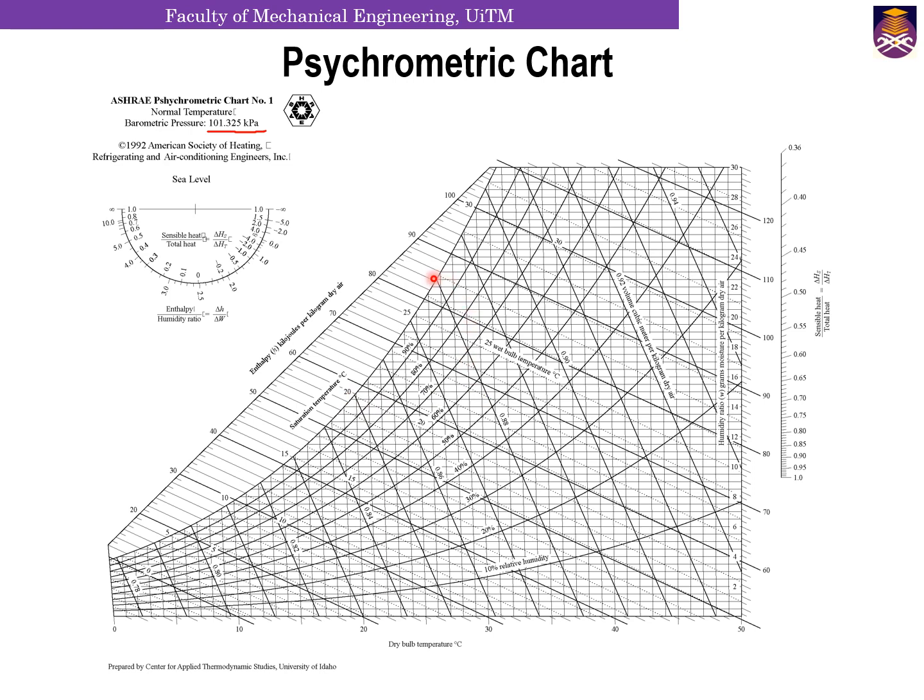The other property that you can get from the psychrometric chart is your specific volume. Those lines are represented by this darkened line here. So you have 0.94. As you go down, it reduces to 0.93, 0.92, 0.91, 0.90, and so on.